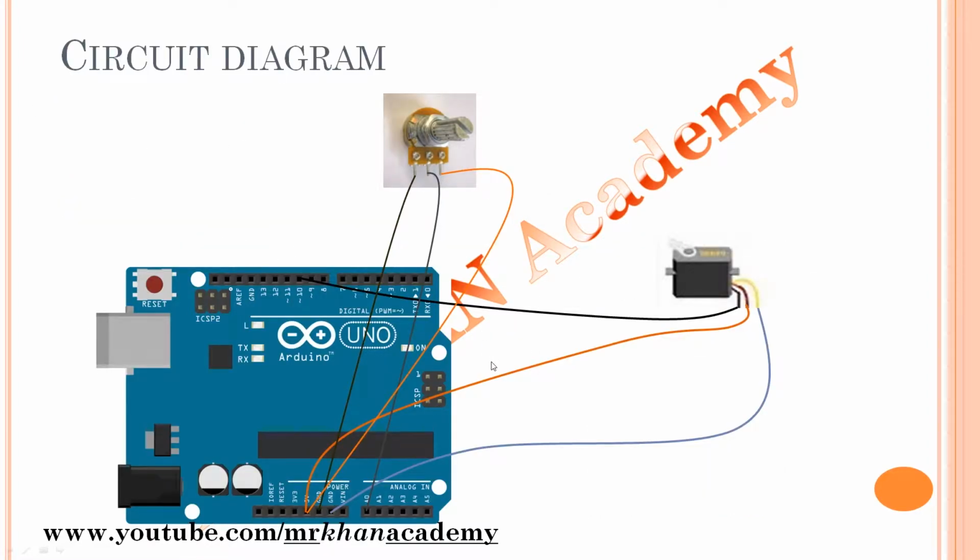Now, for the circuit diagram of the first project, we can see that for the potentiometer, the first wire, on the left-hand side, we need to connect with the ground. The center one is the signal which is sent to the Arduino board, so I am using the analog A0 pin, and the last pin we need to connect with the 5V positive supply. Similarly, for the servo motor, the first wire we need to connect with digital pin number 10. The center one we need to connect with the 5V positive supply,